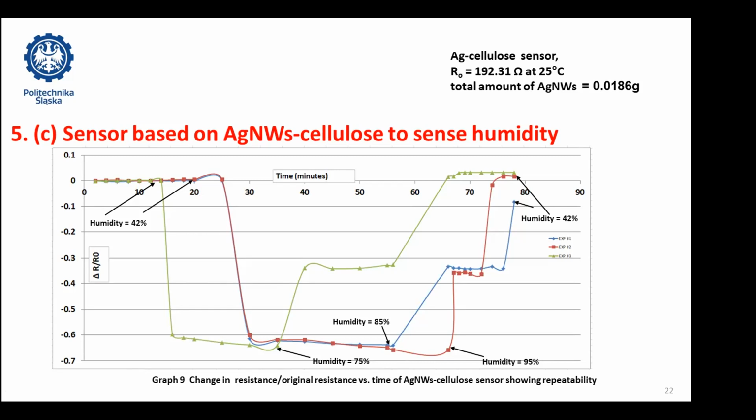So here I will propose an idea that there is a maximum limit to which my sensor can swell, and this is defined by a critical value of moisture. For example, let's say the critical value of moisture is 72 or 73%. Below this critical value, swelling of my sensor is directly proportional to the moisture content. That means resistance decreases with the increase of moisture.